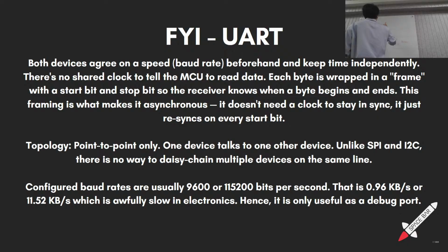The baud rate or bit rate is usually set to standard numbers, usually 9600, or 115200. Like when I use the ESP, I remember typing in something and then 115200. Yeah. So usually you've got your baud rate, which is like 9600.